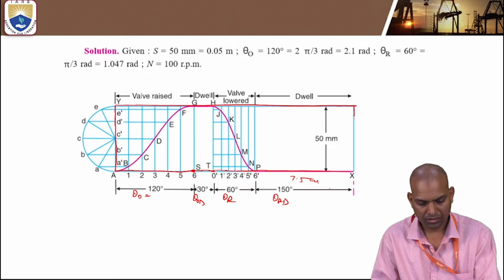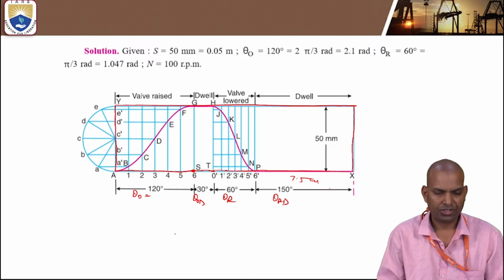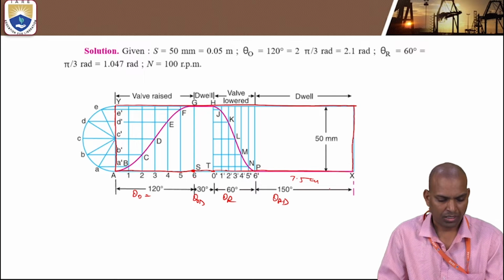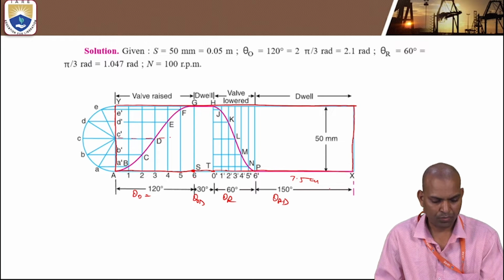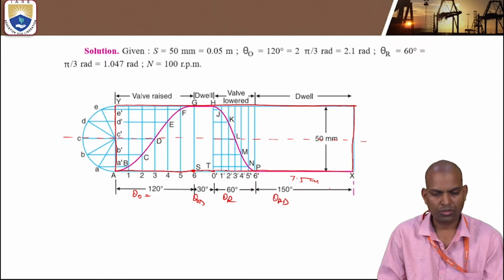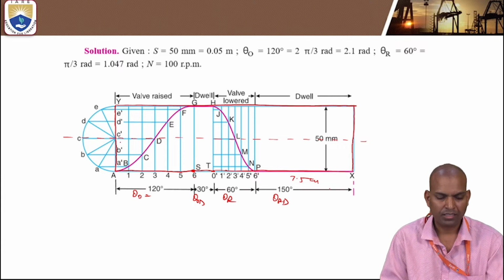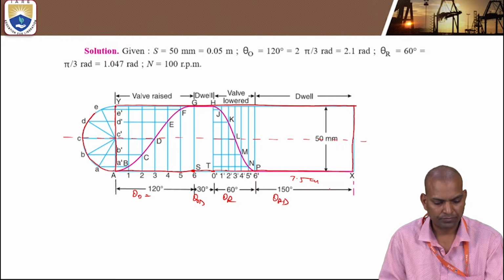So draw the complete x and y axis. Okay, rectangle box. Now it is SHM motion. The SHM motion line is how to draw the SHM displacement curve. Take the y-axis length, draw a center line, and off of this, 25 millimeters, draw a semicircle.